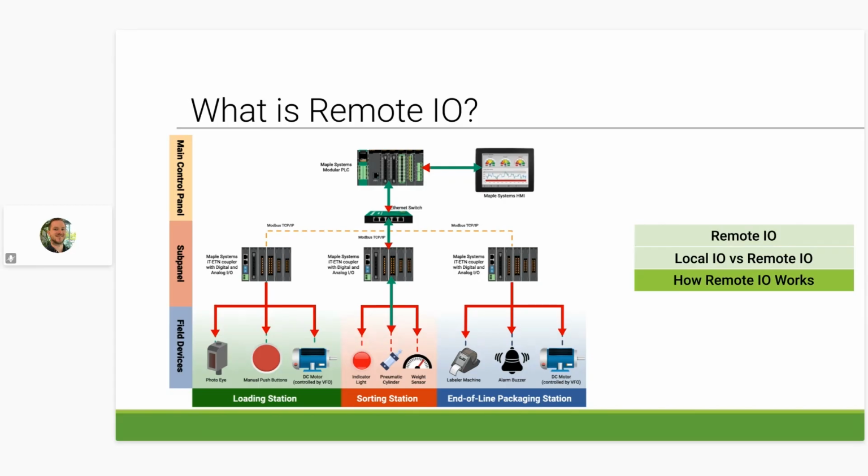The HMI is able to communicate to the PLC, which is connected to the local I/O, controlling nearby devices. Then, with the Ethernet expansion module on the PLC, it is able to communicate over a larger network to the remote I/O chassis, which in this example also communicates via Modbus. These remote I/O chassis can be much further away from the local I/O as long as they are within the range of the Ethernet network at the facility. Then finally, from there, the remote I/O each controls their own independent station, thus spreading more I/O throughout the facility. The communication module serves as a bridge which then transfers all processed data to the PLC through a single cable.